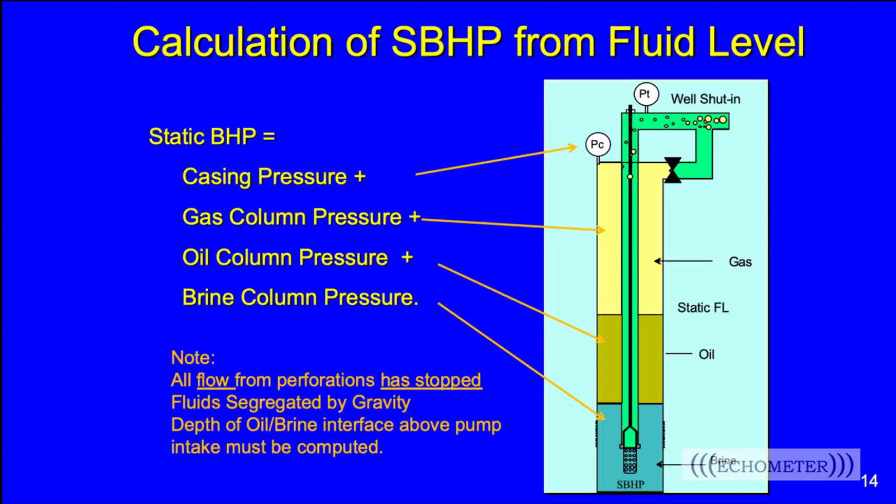Perhaps you have a SCADA system out there and you're measuring the surface pressure on the well, the casing pressure. And even with that, you could just monitor the surface pressure. And when it quits changing, you have an idea that the well's staticed out. So if you've gone out there and you've shot a few liquid levels over a period of days, only that very last one should be used as the static shot in your calculation.